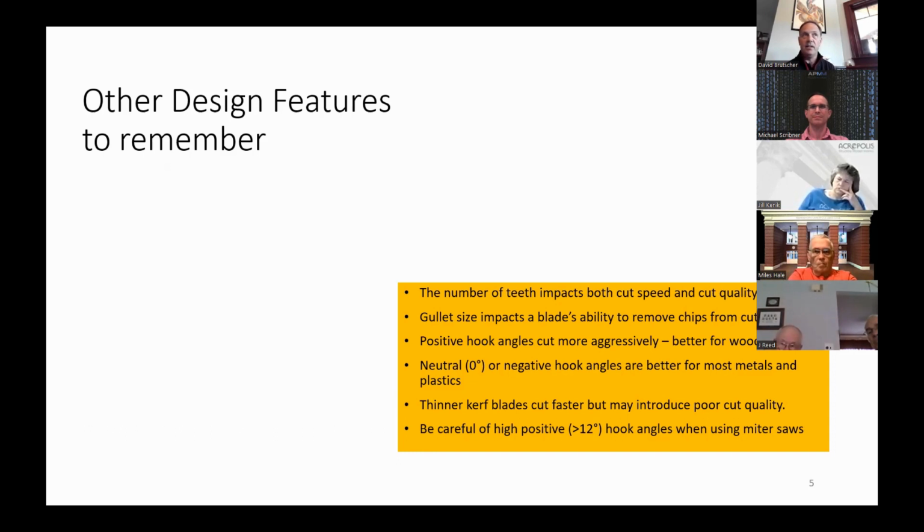What we know is that aluminum, because it is softer, really benefits from the much higher tip speed and much lower chip load of a wood cutting saw versus a metal cutting saw. So anybody looking at cutting aluminum, I believe it's perfectly fine to put those on a table saw or a miter saw that's designed for cutting wood. Some of the manufacturers might not like the fact that you might foul your commutator brushes, things of that nature, but from a finish standpoint and the